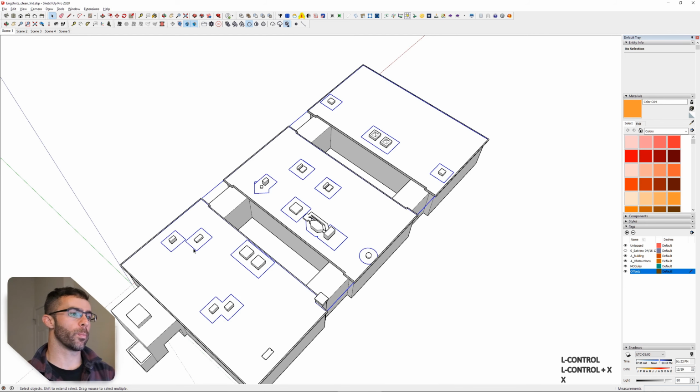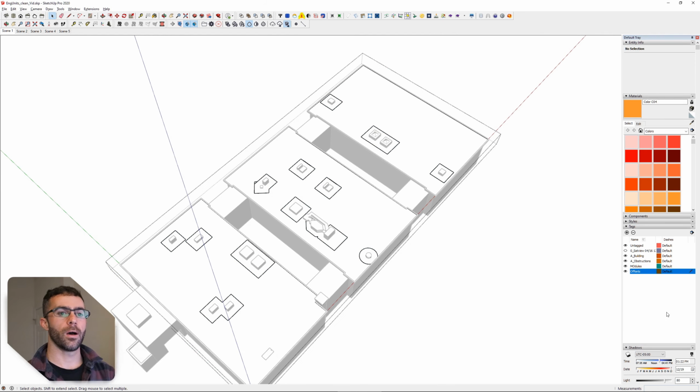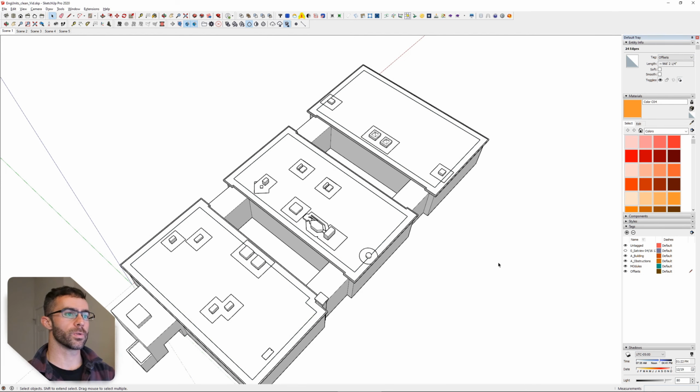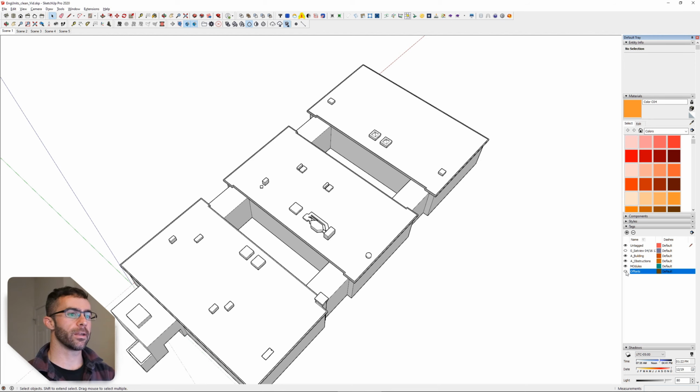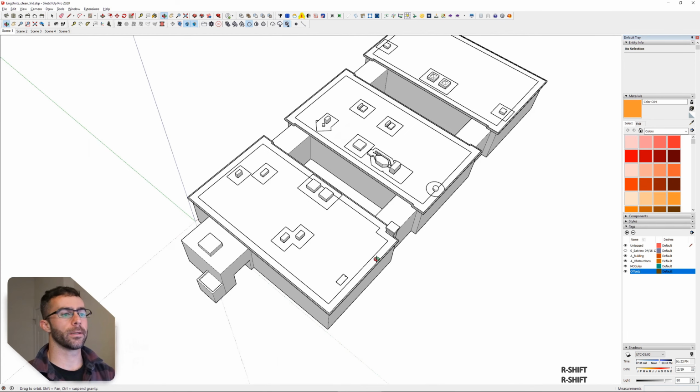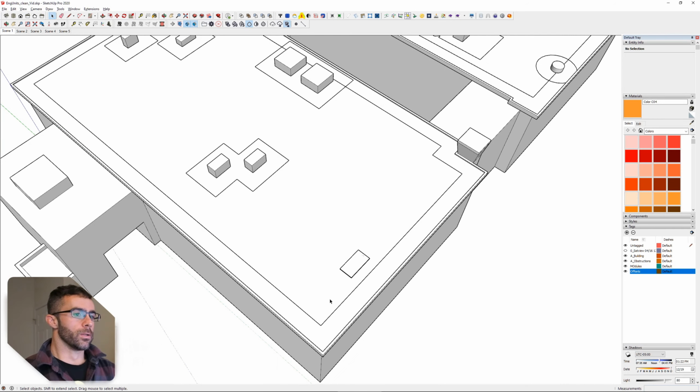I actually want to go back into our offsets and obstructions group. Then we're going to do paste in place. So now we know that that has fallen into the offsets group as well. So later, when we're trying to show the model in a clean form, you can just hide your offsets and all these lines go away. So now we know we have a 4 foot clearance. So where do we begin our module layout?